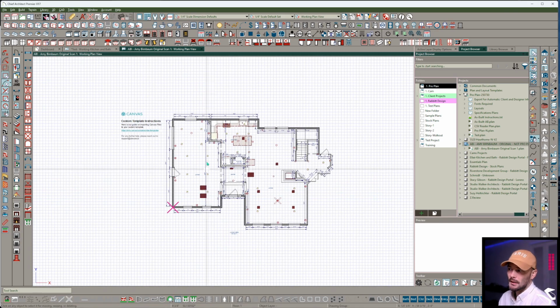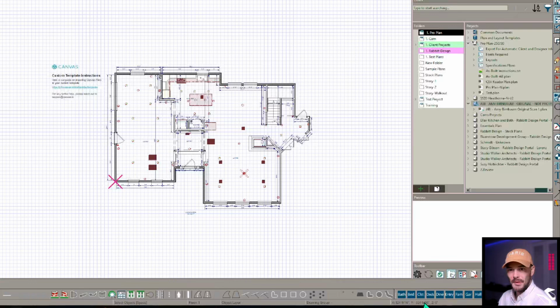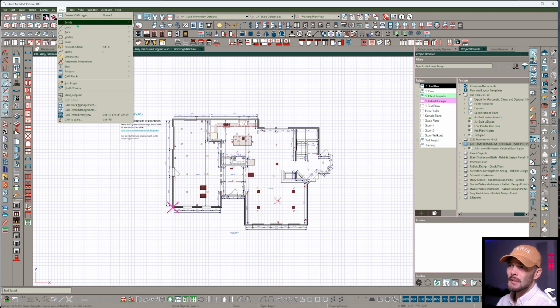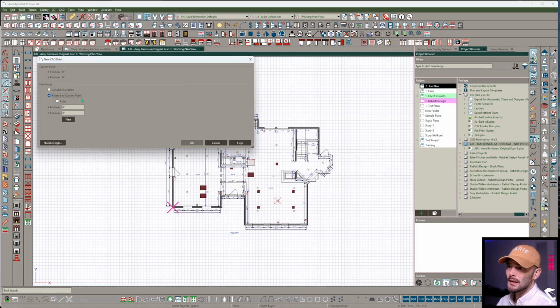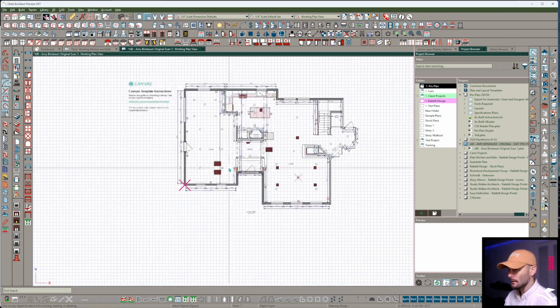It saves a little bit of time, but in case you don't have your building oriented in a way that you know where 0 is on the sheet, and what I mean by 0 is X position 0, Y position 0, okay? So with that in mind, I'm going to get in the CAD menu, points, input a point, make it an absolute location 0, press OK, and we can see here that was already on the screen. I didn't do that. That was already there from Canvas.